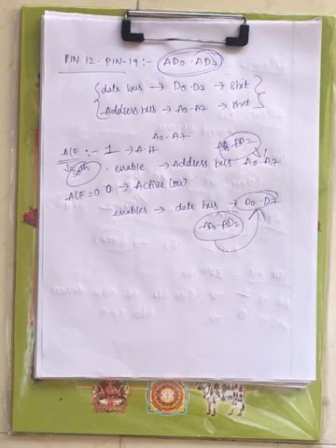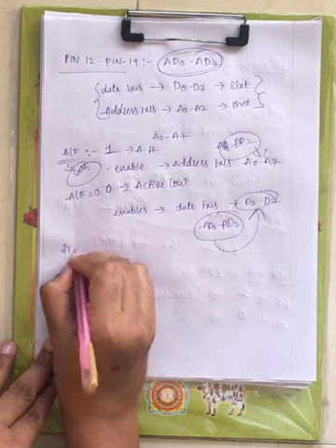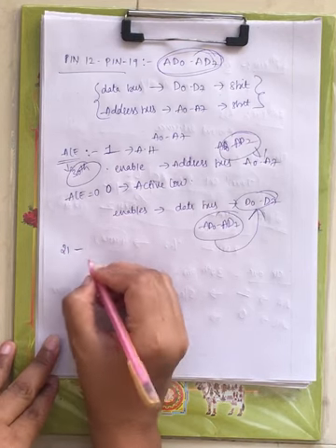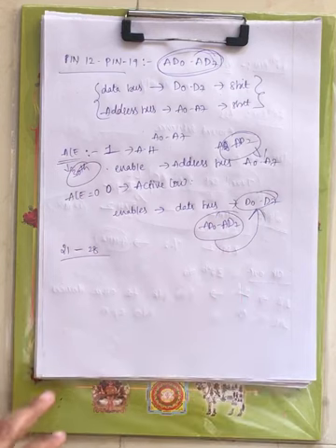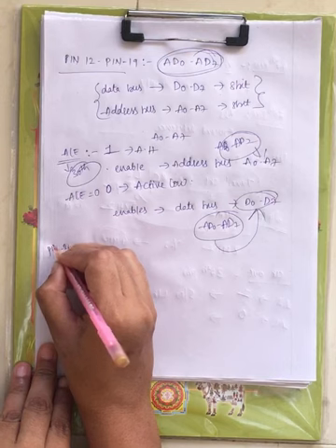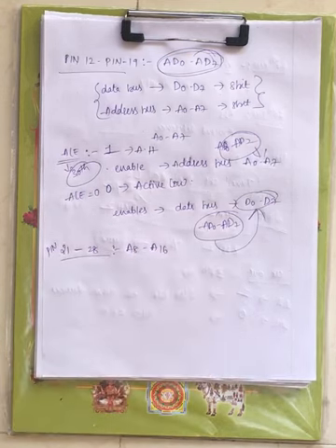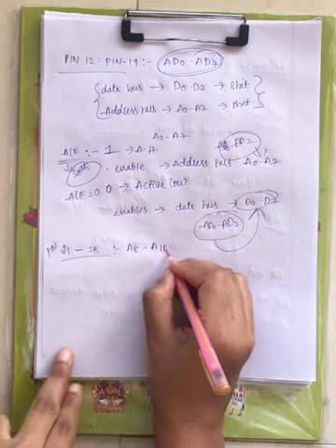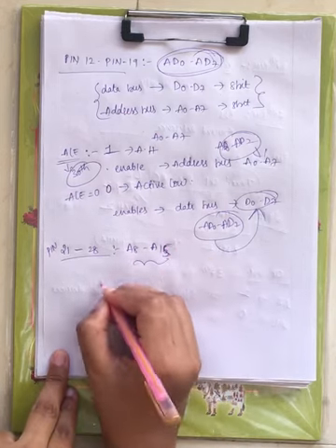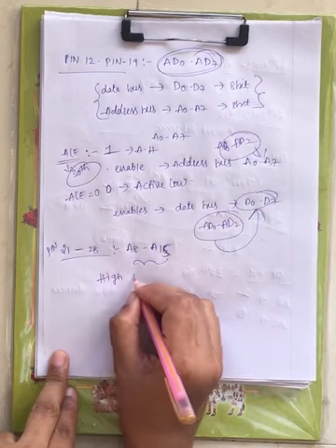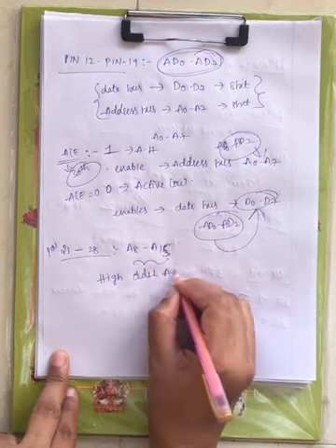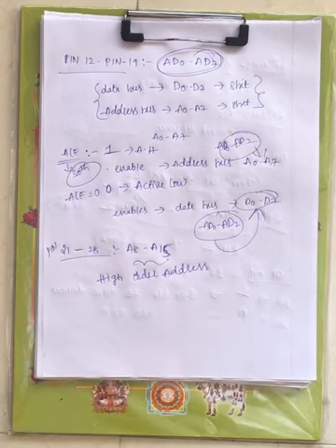And next we have from pin number 21 to pin number 28. What do you have? A8 to A15. Now this will carry the higher order address, from A8 to A15, the upper higher order address.